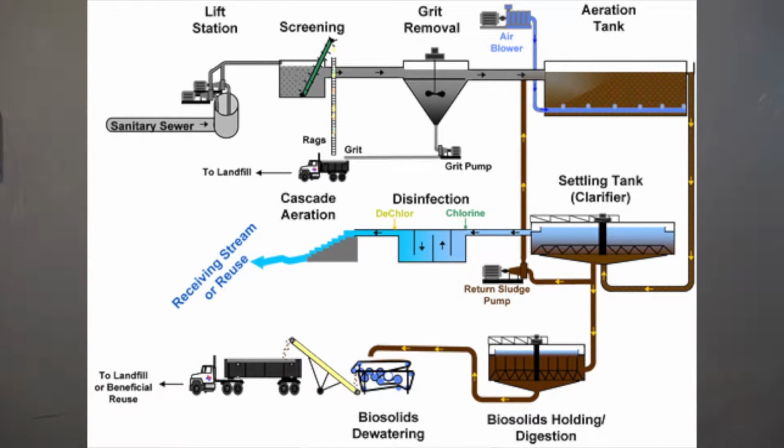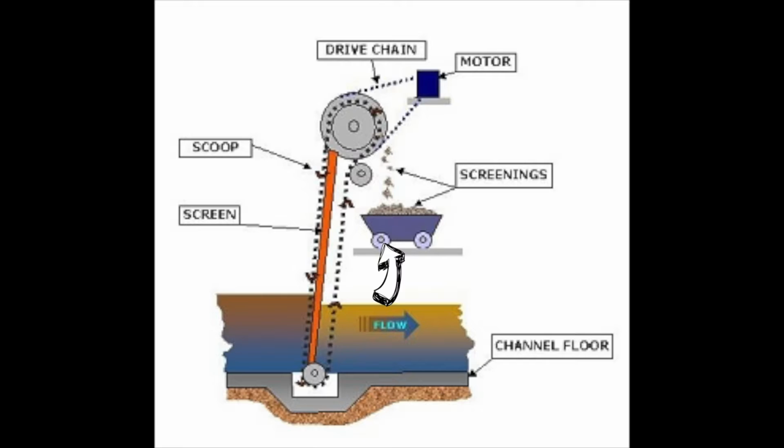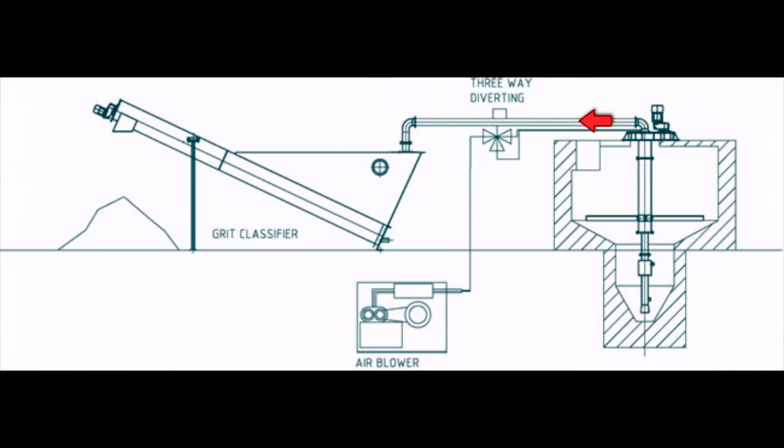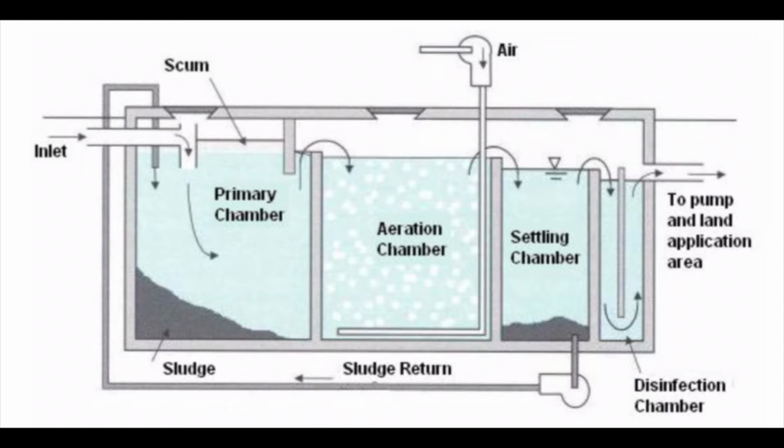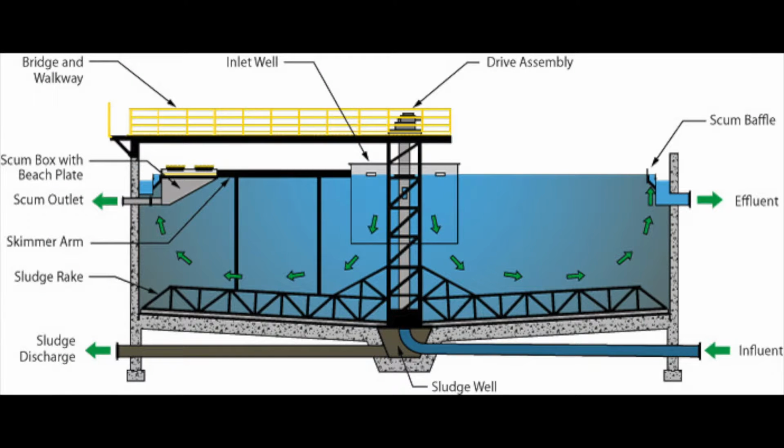In a standard wastewater treatment plant, wastewater normally has to go through several stations in order to be treated and become clean water. The raw wastewater will first enter the inlet screening station, where solid non-biodegradable substances are removed. Then the flow will pass to a grit trap, where grit is removed to a classifier, dewatered and compacted, before disposing into a skip. After settling the grit, the wastewater will flow to a forward pumping station, which will then be pumped to an aeration tank and to the clarifier.